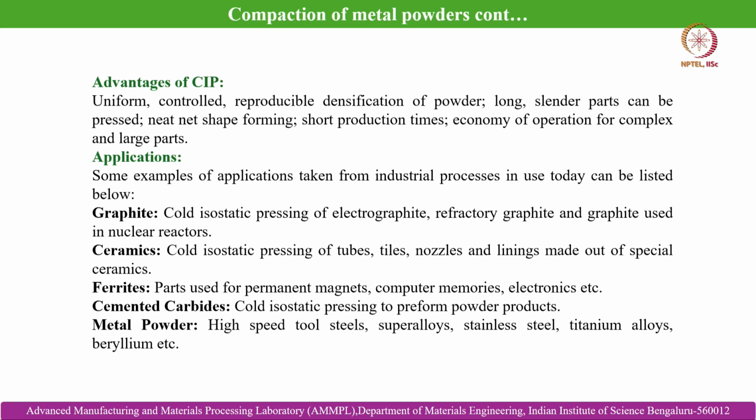pressing technique. So, the advantages of CIP are: uniform, controlled, reproducible densification of powder, longer slender parts can be processed, near net shape forming, short production times, and economy of operation for complex and large parts.